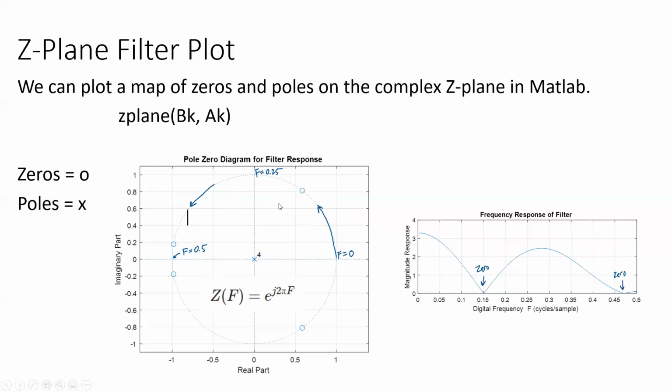And so the reason why this pole zero diagram is so useful is that by looking at it, you don't really know what AKs and BKs coefficients are going to get you a certain response that you want. But it's very easy to look at this pole zero map diagram and just say, oh, okay, I want a very low frequency response down at low frequencies. So I want a low magnitude. So we'll put a bunch of zeros down here, and that'll pull everything down at these frequencies.